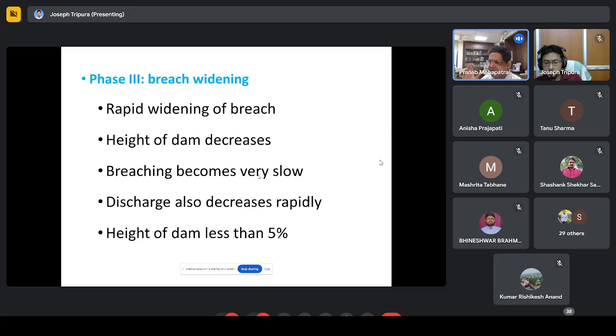Okay. So the engineers came in a helicopter. They put some stones on the levee wherever it was broken. On top of that, they just threw those stones. They dropped heavy stones from the helicopter, and that way they tried to close the breach. Please note that if we are in phase 1 or phase 2, probably we can control the breach. We can try to close the breach. But if we are in phase 3, it is very difficult to repair. We cannot control it. In that sense, identifying these phases is important. Okay, let us go to the next.